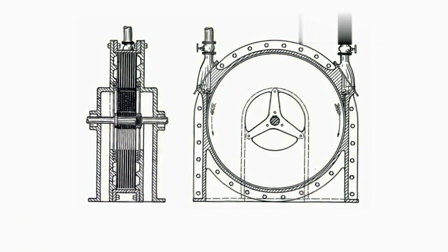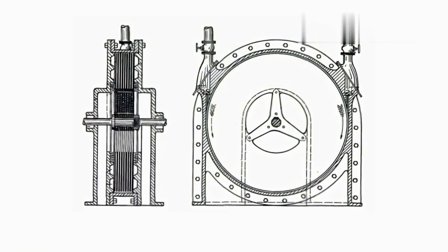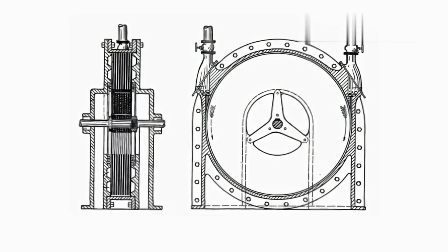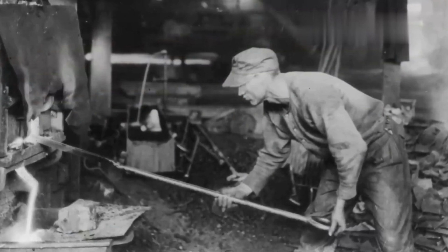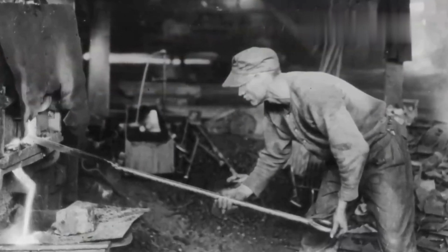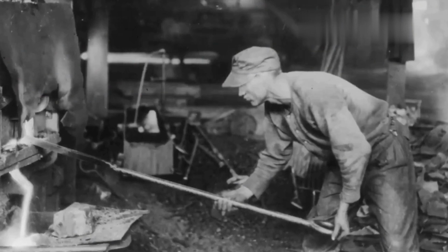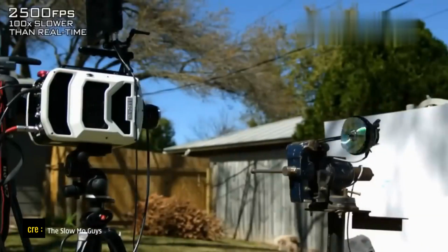Perhaps the most crucial reason why the Tesla turbine could not become widespread is that Nikola Tesla was ahead of his time. He created a machine that required a type of material that his era could not provide. Even the best metallurgists of Tesla's time could not manufacture discs for the turbine that would remain unwarped during operation at speeds of 35,000 revolutions per minute. Warped discs would create chaotic flow patterns, rendering Tesla's design impractical. Looking at spinning CD discs at high speeds provides an analogy to understand the point I am trying to convey.